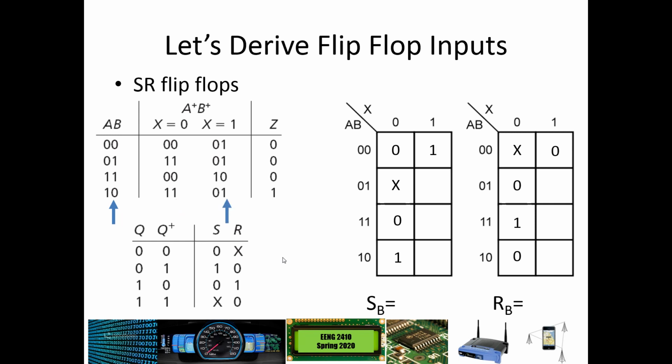Then we move over to the x equal 1 column. We have a 0 to a 1, which gives us a 1, 0 logic. Then we have a 1 to a 1, which gives us x0. Then we have 1 to 0, which gives us 0, 1. And then we have 0 to 1, which gives us 1, 0. This logic allows us to do a little bit of grouping. Here we see the groups that we can make on those K-maps, and we get x a prime or a b prime. And then on the right hand side we get just a b.